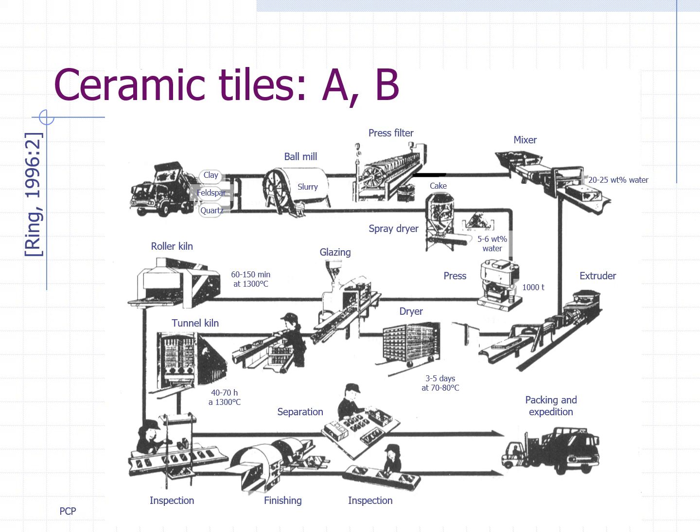Alternatively, a slurry can pass through a spray dryer and render granules with 5 to 6% water, which are pressed into tiles. It follows a glazing and sintering step. The latter is held in modern days in the so-called roller kilns in much shorter times in a continuous fashion.